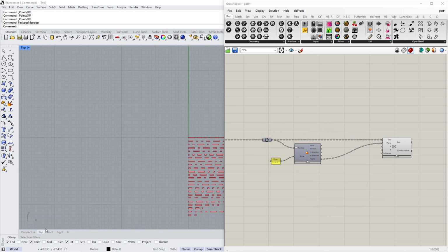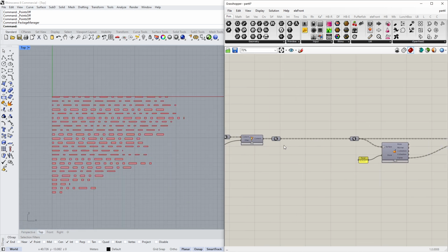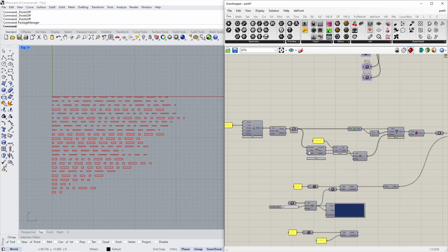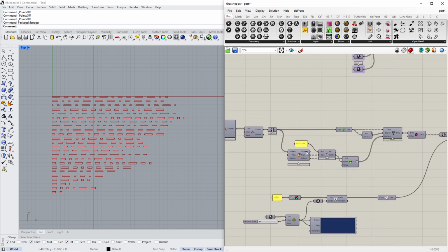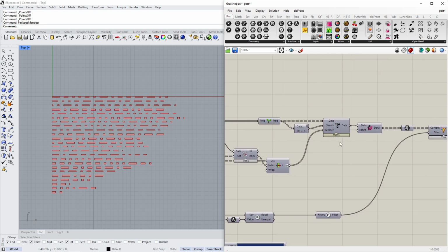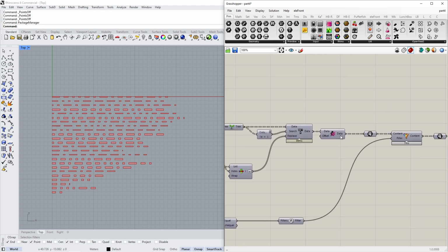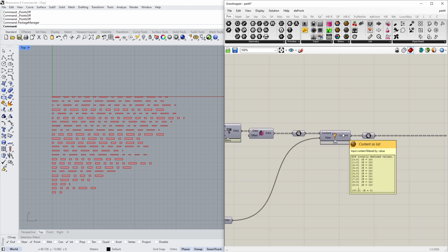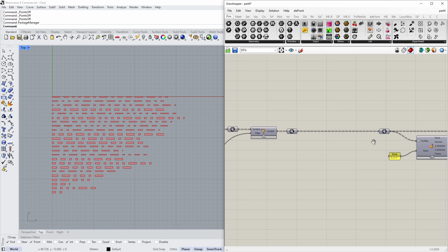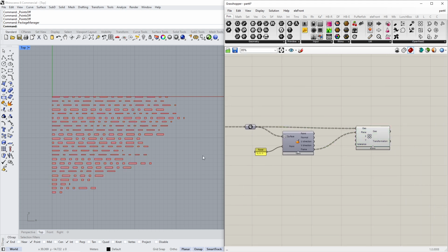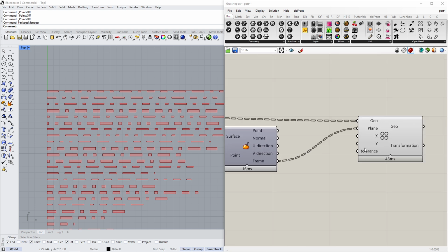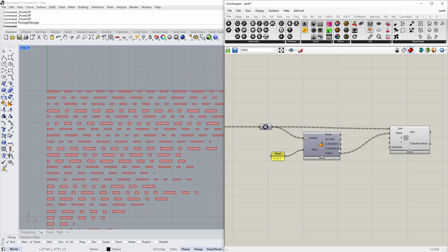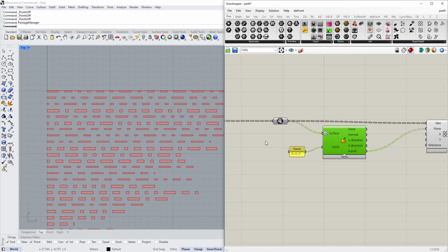And the nice thing is that because we reordered again, instead of having just a simple list, we used the data tree key to reorder our list into the data structure it had. And because it's still organized by rows, this component will take that into account and will basically lay out per row all the tiles with a spacing X and Y. So it's very helpful, right?